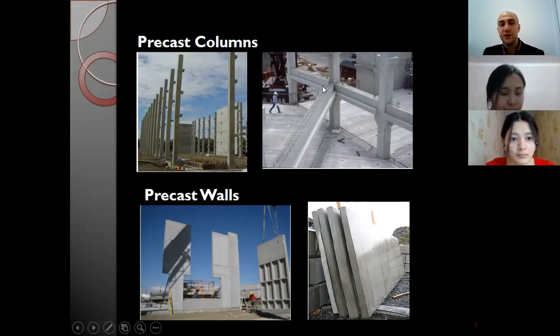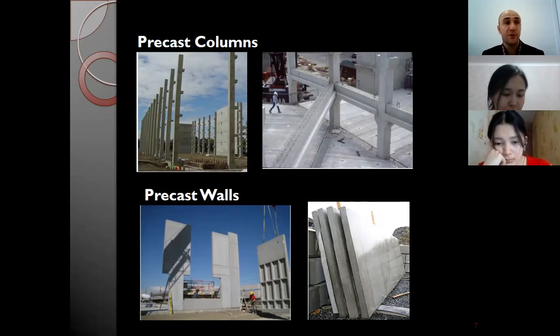The foundation can be prefabricated. In prefabricated constructions, foundations can be prefabricated or monolithic. It depends on the soil conditions, on the absence or presence of a substructure of the building, on the water location beneath the foundation level, and on the hardness of the soil.